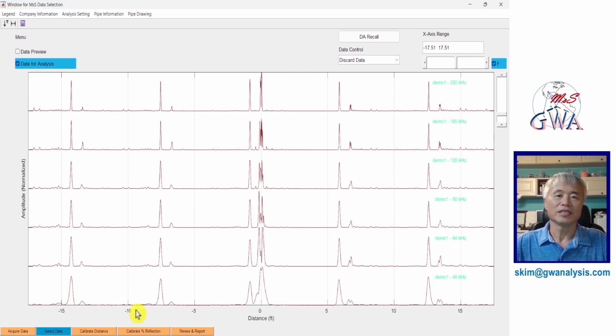For data analysis, we need three calibrations: distance, amplitude, and attenuation in the next step. However, it takes time and is difficult to do with the 6 video data sets, especially since those processes are highly dependent on the inspector's experience and knowledge. The easy way of calibration is drawing the pipeline by matching the ultrasonic signal and the geometry feature.